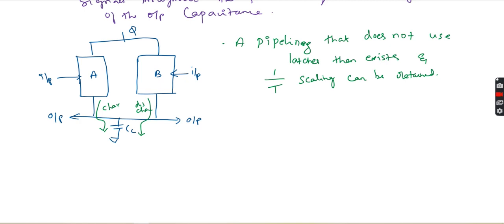So therefore, we cannot derive it directly from the output of the stage being de-energized. So further, the control for the de-energizing path must instead be controlled by a signal derived from the output of the following stages in the pipeline. In this pipeline, a pure copy of the signal is sufficient.